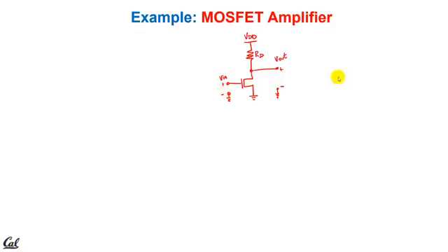Okay. So let me jump right away and replace this. So we're going to have our ground, plus minus V in. This is also going to be the gate. And we're going to have our G times VGS as the value of that. And we're going to have our little resistor, RD, and VDD. This is going to be our V out.